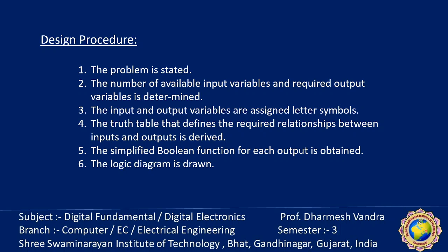statement. Remember that when a truth table for a combinational circuit consists of inputs and outputs, the ones and zeros are obtained from the 2 raised to n binary conditions available for n input variables. It might be determined that some input combinations are invalid, so we have to consider them as don't care conditions. These don't care conditions are also useful to simplify the Boolean function. The output functions specified in the truth table give the exact definition of the combinational circuit.